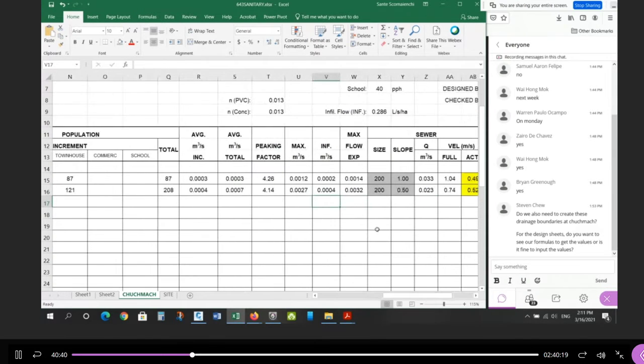And then for each pipe, you have the dry times peak plus infiltration. Dry times peak plus infiltration. And that's all this does. It adds up these two columns. So 12 plus 2 is 14, 27 plus 4 is 32. Now it looks like there's a bit of a rounding issue, right? 27 plus 4 is actually 31, but we're looking at 4 decimal places, it's rounding. So there's a bit of a rounding issue, but it should work out.